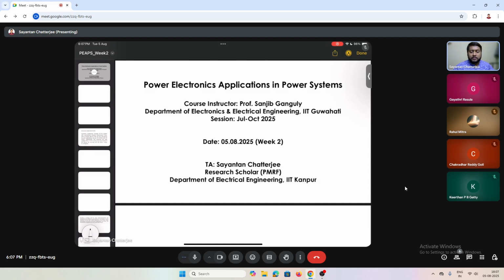Nowadays Power Grid is working on various aspects where these cross arms are targeted to be reduced, while people work on the material aspect to improve the dielectric strength of these materials, so that the right of way can be reduced, because attaining the right of way has become a major issue.